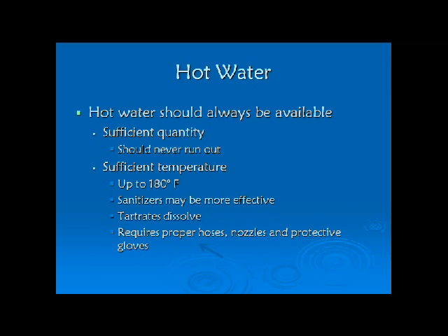And of course, the experience there also is that if you're in the middle of cleaning something and the water starts getting cool, you generally don't stop and wait for it to heat up again, but rather just keep going, and eventually you're just using cold water. And as far as the temperature goes, I have seen systems that again will dispense water up to 180 degrees, and at that temperature you are almost able to sanitize by heat alone.